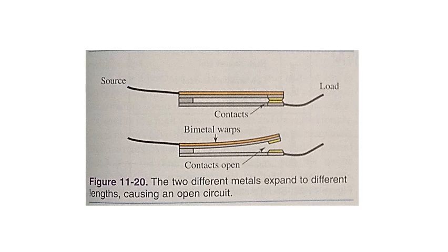According to the National Electrical Code, DC motors over 1 horsepower should be protected by a fuse or a breaker that is no more than 150% of the full load current. The size of the conductor feeding the motor should be able to carry at least 125% of the full load current.